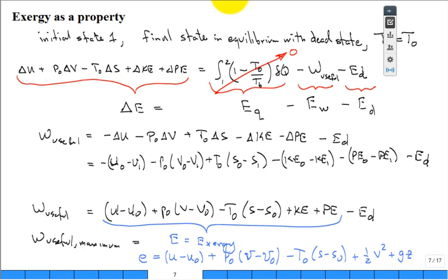I put this on a per unit mass basis, so all of these are lowercase except for the T, and I think the P in this book uses lowercase p anyway for pressure. But what do you mean by this naught? Well, you have to talk about some sort of temperature that's our ambient, environmental, exergetic, zero state temperature. Typically 25 degrees C. Been in a chemistry class?